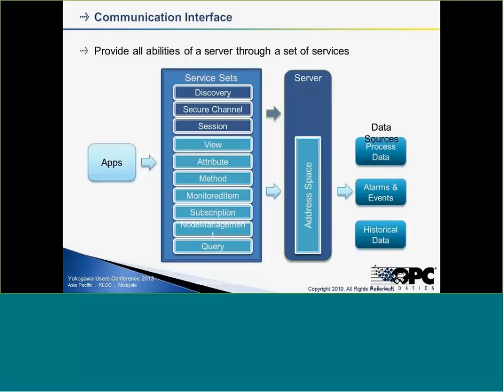So there's a lot of things on this, and I'm covering just a very quick overview of that. But if you think about what we've said, from an application standpoint, you still have an OPC server that understands how to talk to those underlying data sources, whether they're for process or discrete or alarms and events or historical data or devices. And as Scott showed you in his demonstration with InduSoft Web Studio, the server is the one that understands and basically provides the address space of all of the things that you can access and communicate to.